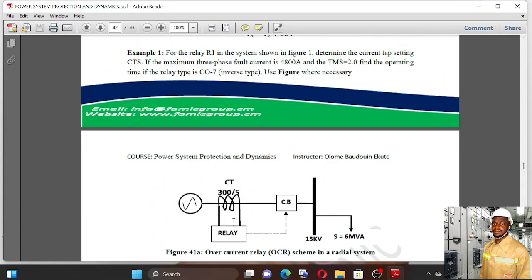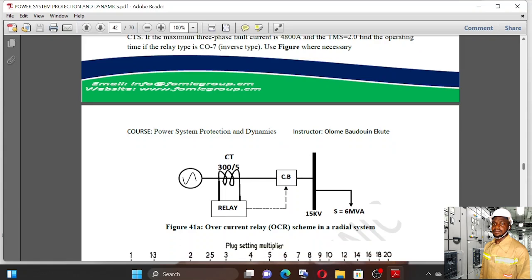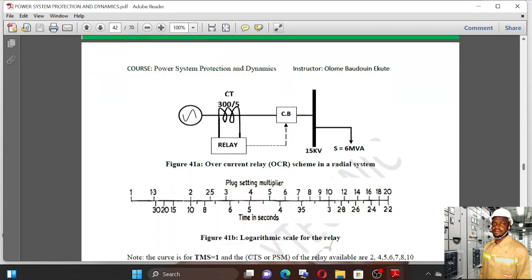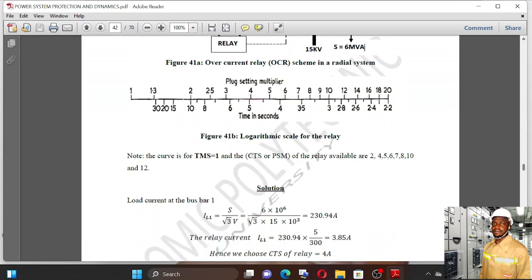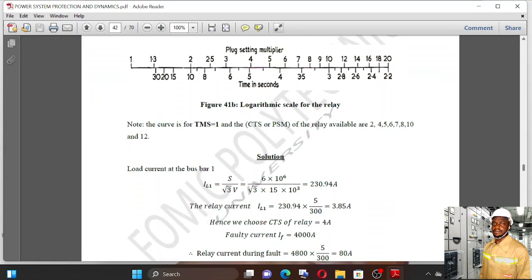Yeah, here it is, the power of that bus. You know, the power of the bus is still the same power which the generator produces. In power systems, energy can neither be created nor destroyed. So the power on the line is constant. No matter if you're using a step up transformer or step down transformer, if you're stepping up voltage or stepping down the voltage, you know, when voltage steps up, current decreases. When voltage steps down, current increases. But when you multiply the two, it will still give you the same power. So the power at that bus is still the power in the whole system.